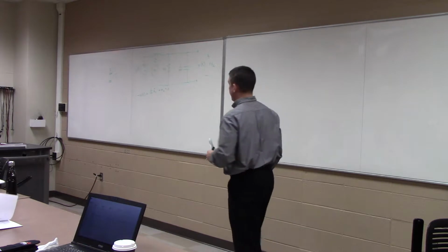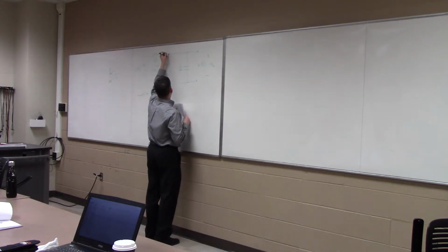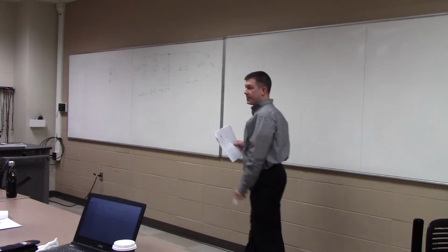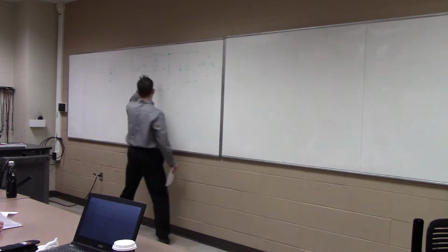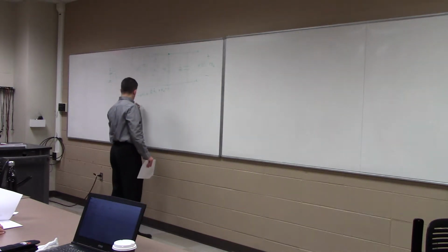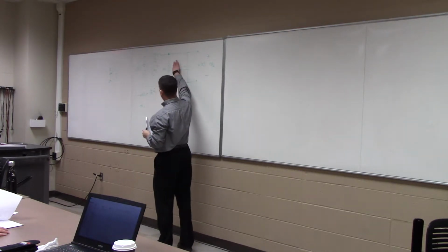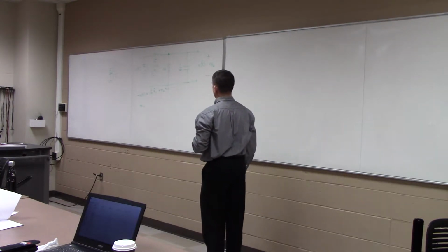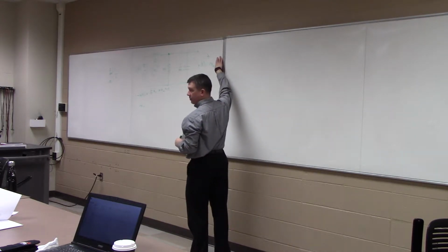So the next one is going to be Kirchhoff's current law. We'll say that the currents entering that node all sum to 0. So what are the currents entering this node? Well, one of them is going to be x1. The other one is the current going through this resistor. V is equal to IR, so current is going to be V over R. It's x2 over 100.